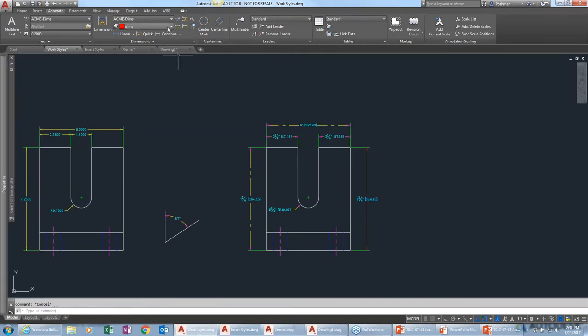Again, that saves a lot of picks and clicks. I'm drawing center lines over here, and then I want to add some dimensions. I don't have to change layers before I place a dimension. I can just start adding the dimensions in, and it will put them on whatever layer you specify here. It's basically an override specifically for dimensions.